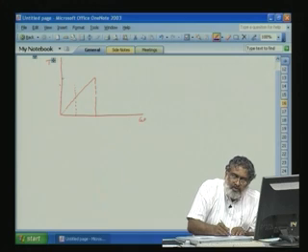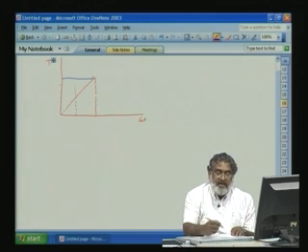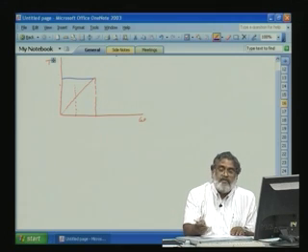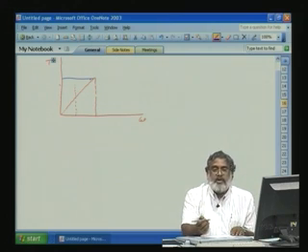So the machine has gone to the maximum torque here, T. Now hereafter we cannot increase the voltage, because if we increase the voltage, what will happen? It may go beyond the rating of the machine. And voltage and current also we cannot increase, because we have come to the maximum torque now.